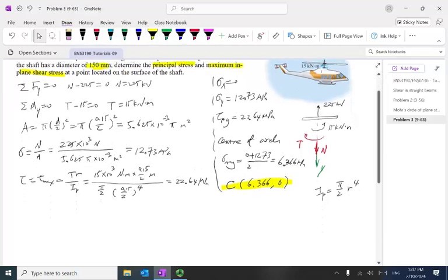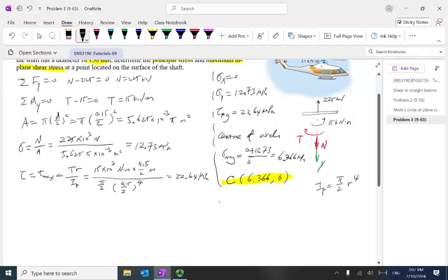The reference point A: sigma x 0, tau xy 22.64. That's point A. Also get a mark, write down this one. And then the radius R. Do it either way by yourself, okay? Like I said, you can use the distance between the points or use the equation.